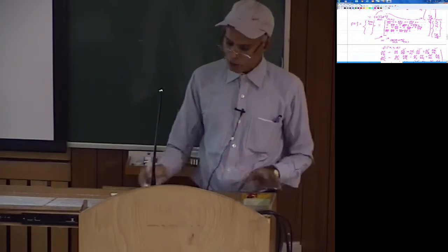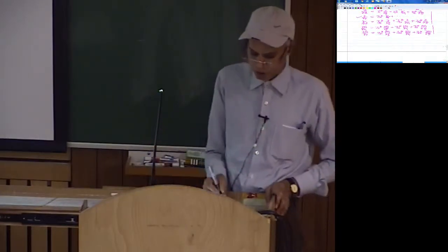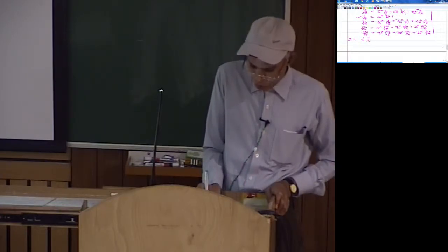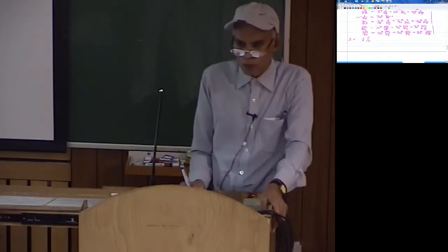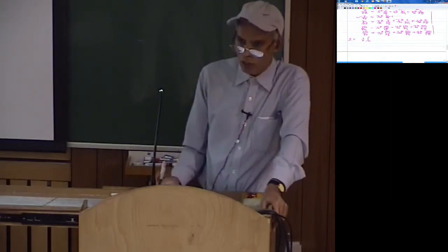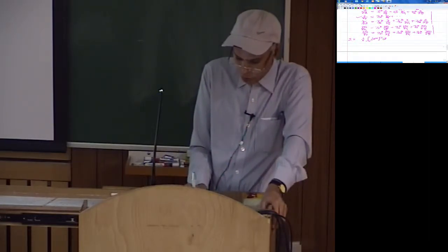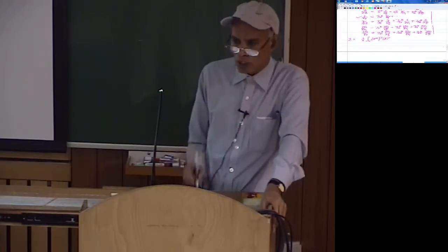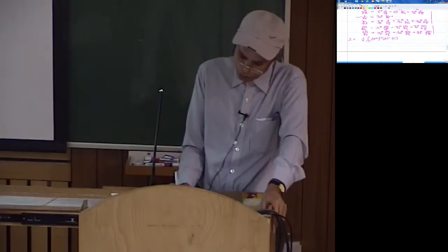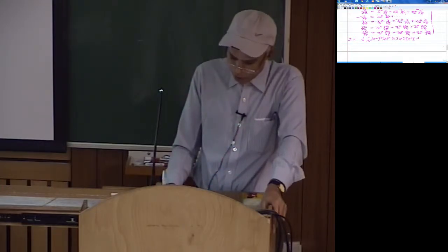Once you evaluate this, now you are ready to substitute this in your integral functional and all of the element level governing equation. So again, if you come back to I, which was half integration over volume, and this was epsilon transpose C into epsilon. Epsilon transpose can be written as epsilon is B into dE. So we will have here dE transpose into B transpose, because epsilon is B into dE, its transpose is this. Then in between you have a constitutive matrix, and then again epsilon, which is B into dE, and then the integration over volume dV.